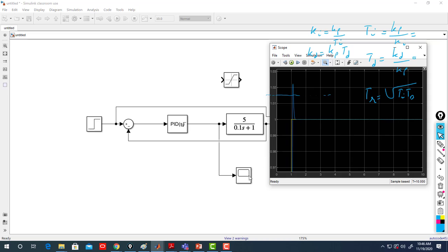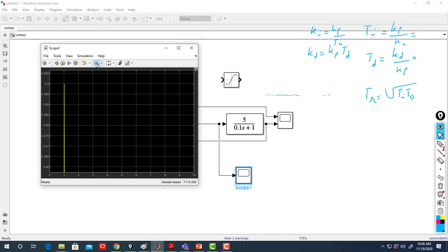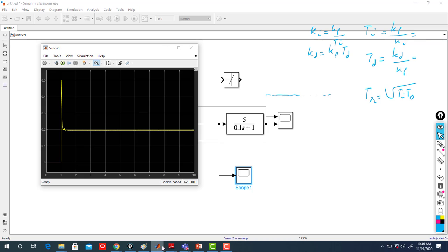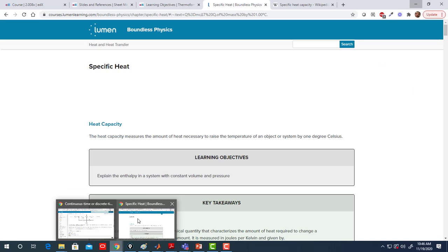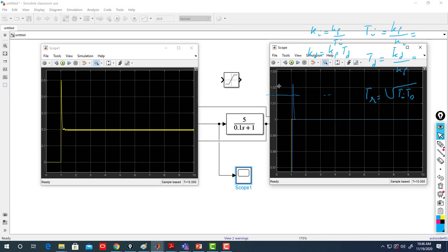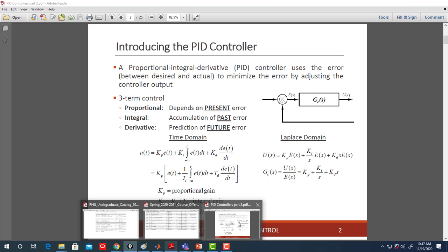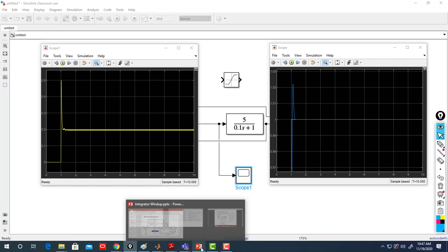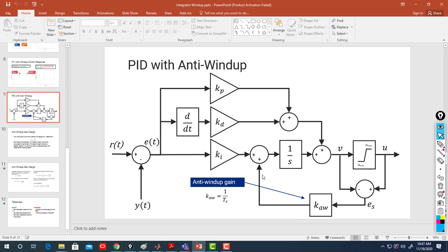So you see it is also better than how it was before. Here is the signal. So then you don't need to calculate a coefficient, but it's more complex in integrating it. But here, thanks to MATLAB, it's possible to do the switch on and off. So usually it's smoother to have a proportional rather than an on-off controller. This is kind of an on-off controller. Here is kind of a proportional controller you are getting.